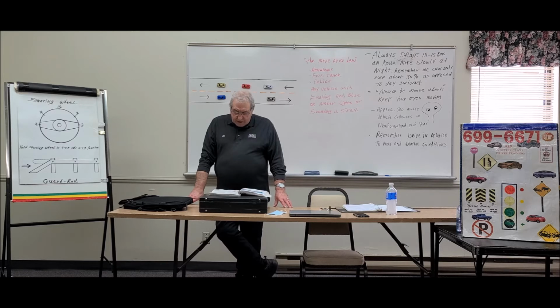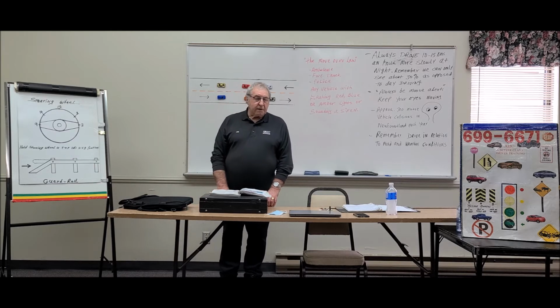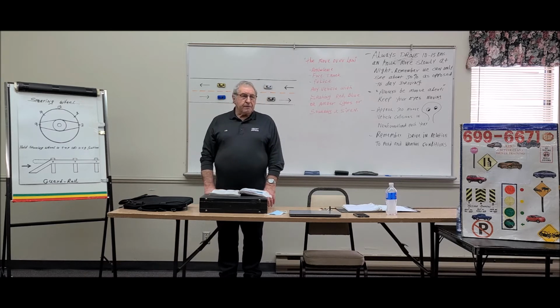The oil pressure gauge, of course, indicates a problem with the oil pressure in your engine, and that's an immediate problem, class. If you see your oil pressure light glowing when you're driving on the highway, immediately get yourself safely off the roadway first, and then turn off the engine, because what might only require a liter or so of oil, which is $4 or $5, could become a problem. If you keep on driving, you're probably looking at a $5,000 or $6,000 engine.